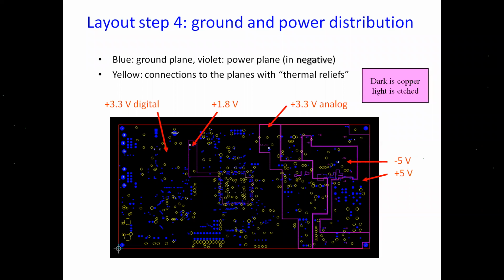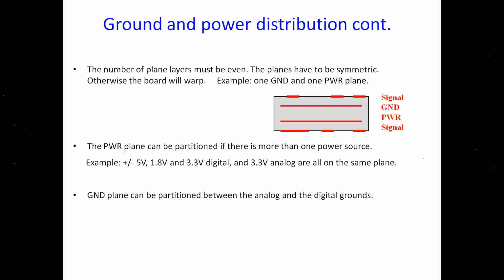Similarly, this same concept can be applied for the ground plane also. The distribution of the ground should be continuous for the proper return current. This typical 4-layer stack up is shown here. Normally, in between signals, we introduce the ground plane or the power plane for making the return path perfect.